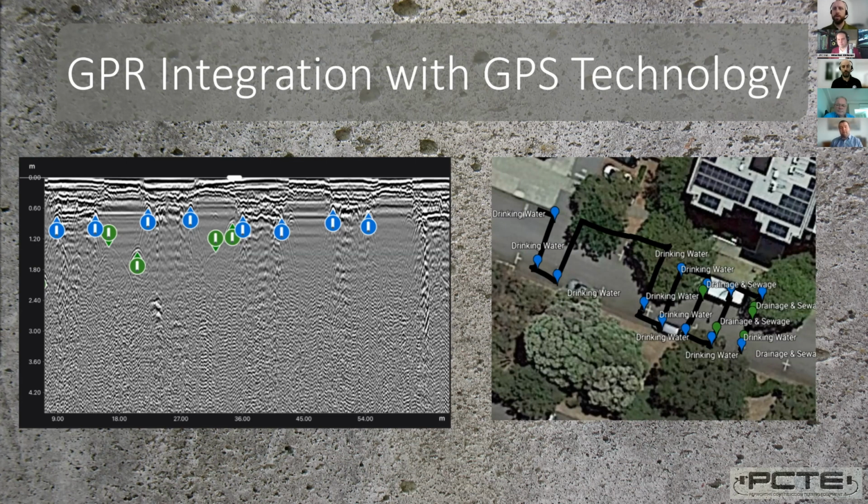on the right. I think this was some scanning work that Ruben actually did in Perth, but we marked several utilities a few different times to see the path of them. This information can be provided to the customer to get GPS coordinates which are accurate with an RTK correction, and the depth of each target can be provided. So this can already be done with the GS8000, and it's a great output of the device. Go to the next one.